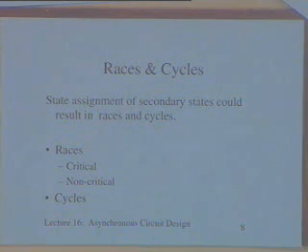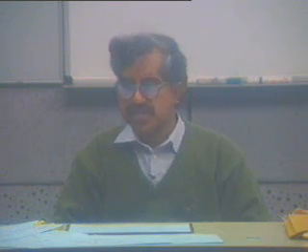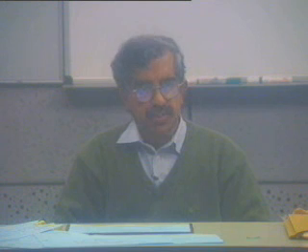It's not difficult to see when a critical race arises. We will discuss that in a moment, but let's first define also the non-critical race. Sometimes you may go through some transients, but finally reach the state that you actually wanted to reach. So then it becomes a non-critical race. You can sometimes permit more than one secondary variable to change, but you can end up in a non-critical race.